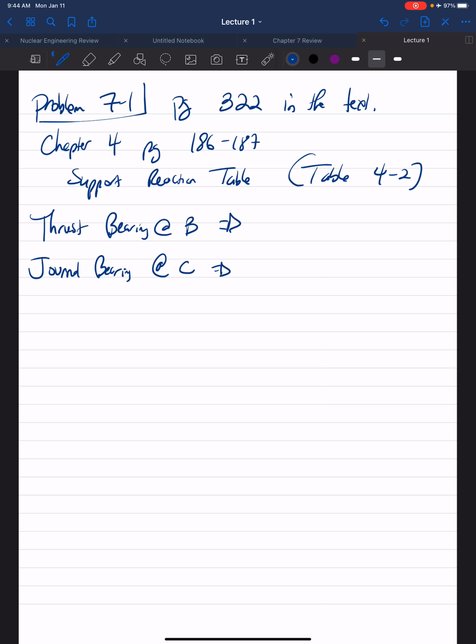And for the thrust bearing, there are 3 force and 2 couple moments, but once again, we can ignore the couple moments. So here we're working in 2D space from the problem set we're working now. So to draw the figure out as a free body diagram, let's start with our shaft.